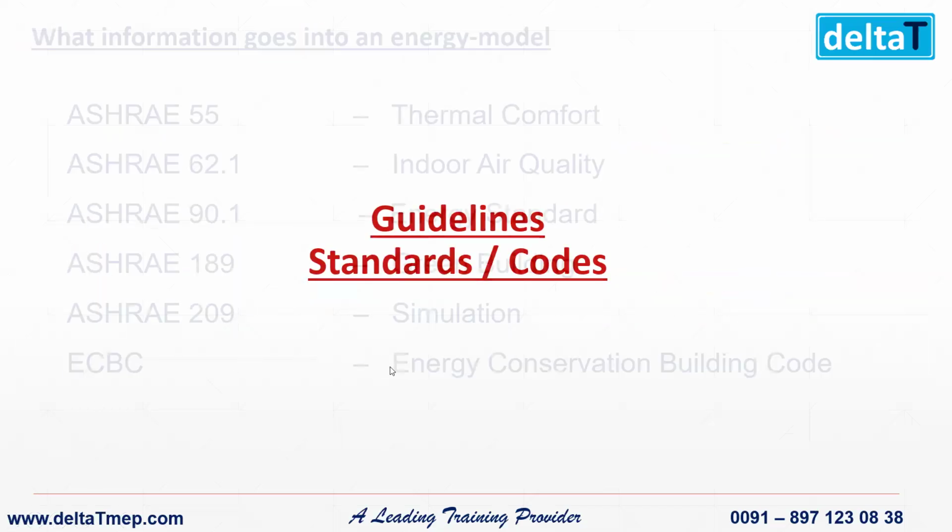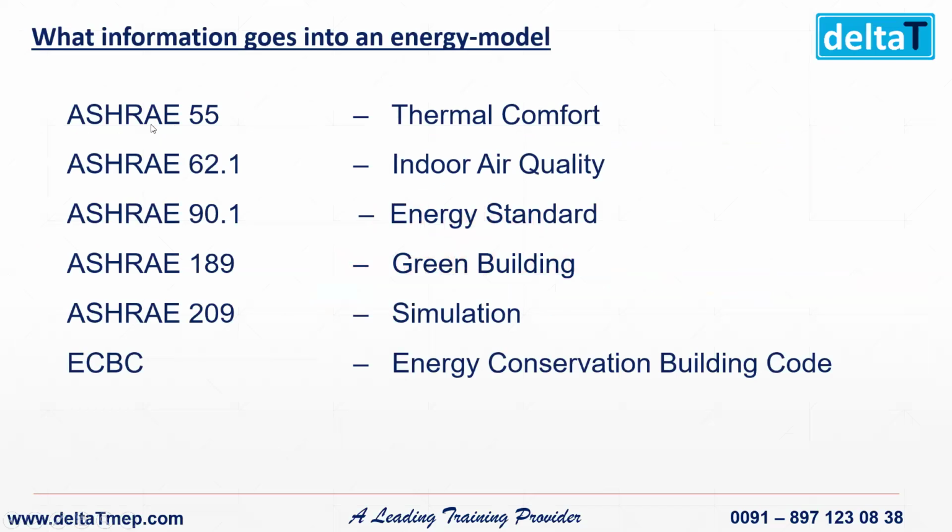Now the standards we use: ASHRAE 55, as I said, is about thermal comfort. Usually, I hope everyone knows, in a room we maintain temperature, right? How much temperature do we maintain? 24 degrees Celsius. And then we also maintain relative humidity, I mean humidity level, right? That is what ASHRAE 55 specifies, so it might differ.